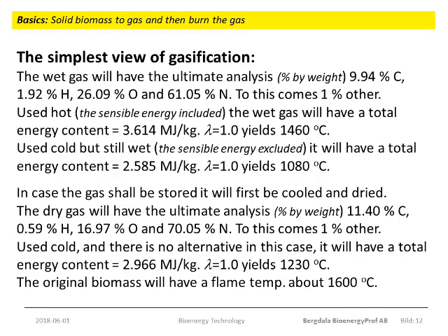To be able to compute the flame temperatures using the computational aid you prepared before, you now have to calculate the ultimate analysis in percent by weight for the different gases. And then remember that if you want to store the gas or transport it, then you have to cool it down, or it will cool down by itself. And then the water will condense and you will get a dry gas.